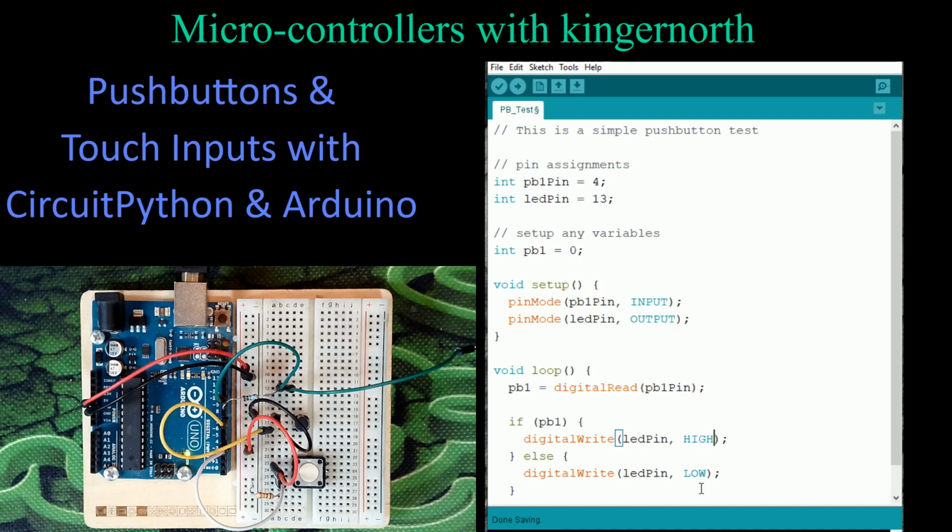And this is the way they prefer to do it in Arduino. They like to use the words high and low for setting the pin values. High just means set it to whatever the voltage is of the microcontroller, and low means set it to common. It gives you something very close to high, very close to the voltage. If it's 5 volts in this case for Arduino, it gives output very close to 5 volts. If it's low, it's very close to 0 volts. Everything in these microcontrollers is just going to be close to something. Does it have to be exact? Not necessarily, but